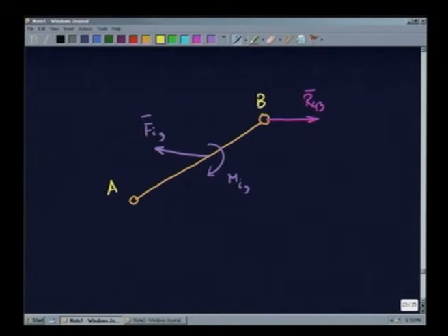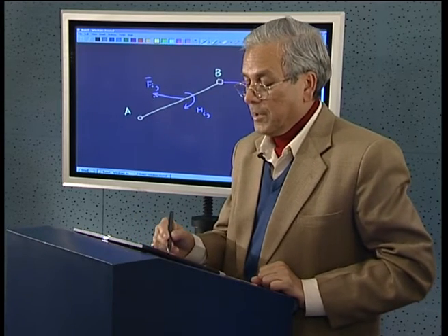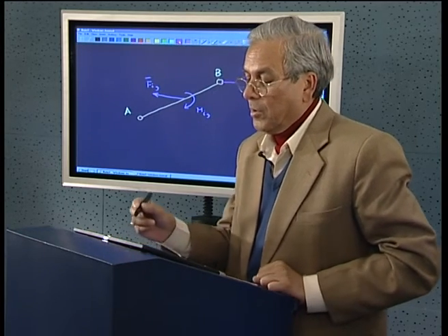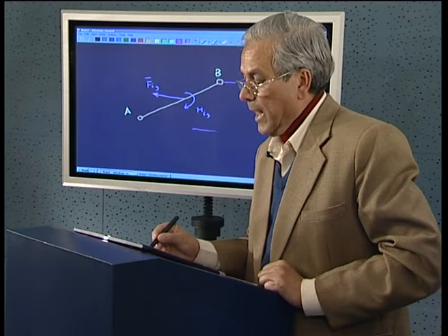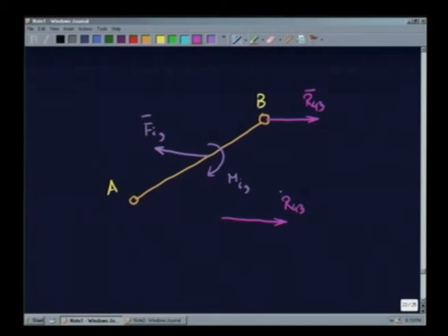Now, this can be easily found out because we know that the system must be completely force free. So, therefore, under the action of this force and this force, its total force should be 0, or we can say that if we add the three forces, they will form a closed triangle. This you know from vector mechanics, and for your benefit, I slightly change the direction, making it this, not to make them align.